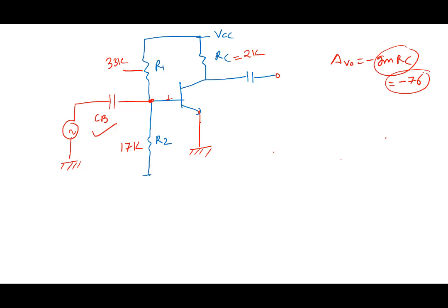Do you see that it's a problematic circuit? I mean, this voltage divider was trying to do what? Generate 1.7. How can you apply 1.7 across the diode here? So you're heavily forward biasing the diode. So the circuit is not properly biased. If you just simply remove RE, the circuit is not properly biased here. You have to keep RE. RE is the one which is deciding the current. So RE is required.